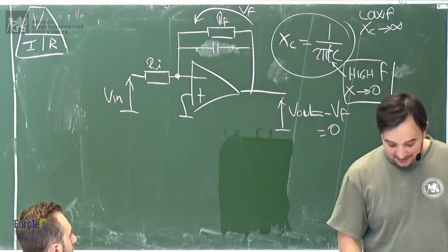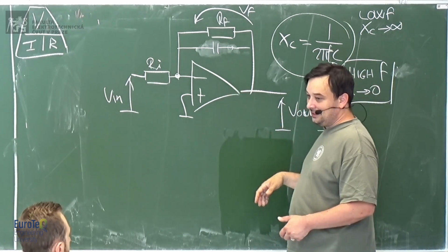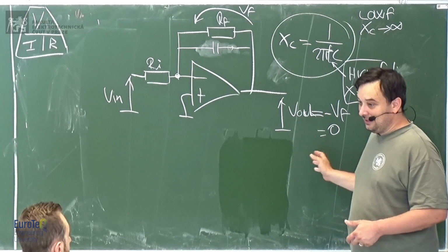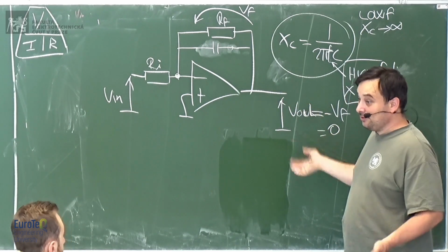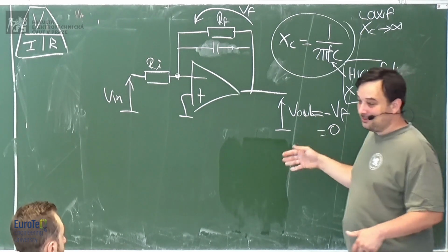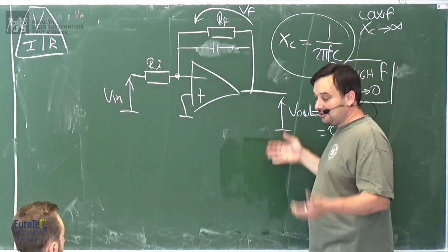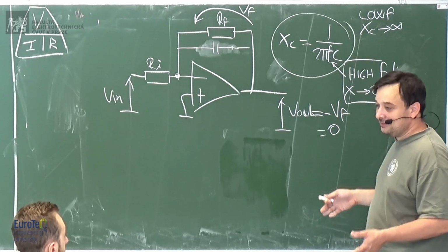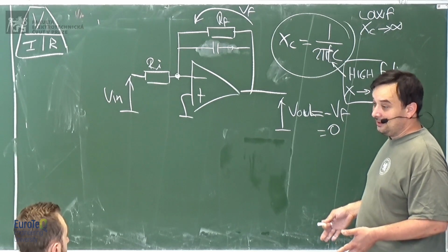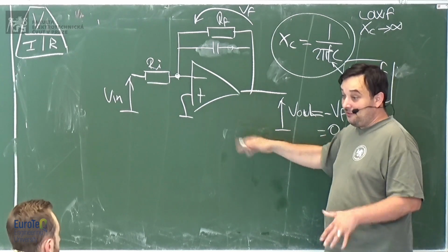So very often, for instance, if you have a very high bandwidth operational amplifier, and it's too large for the bandwidth that you need, it will also amplify high frequencies that you don't want. Yes. Well, you could choose another operational amplifier which is not so fast and doesn't have such a large bandwidth. But if you have to use that one, how can you reduce the bandwidth artificially below the bandwidth of the operational amplifier itself, if you don't need all of that?